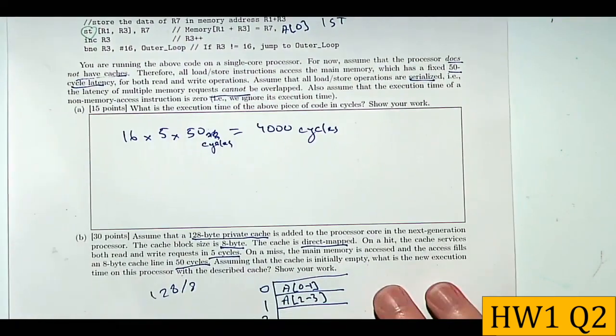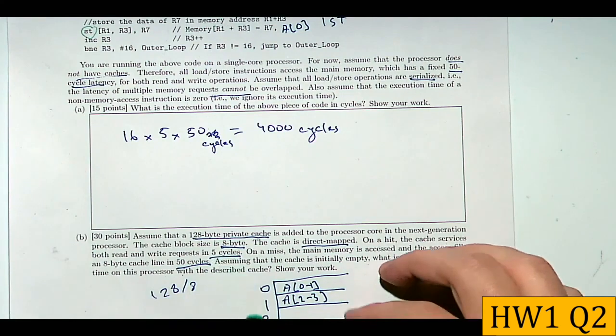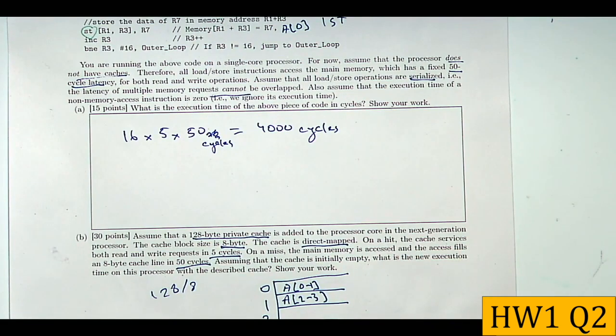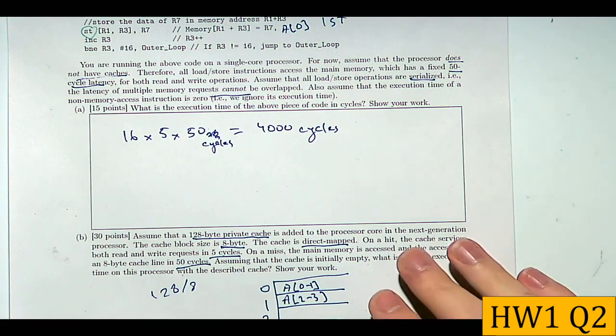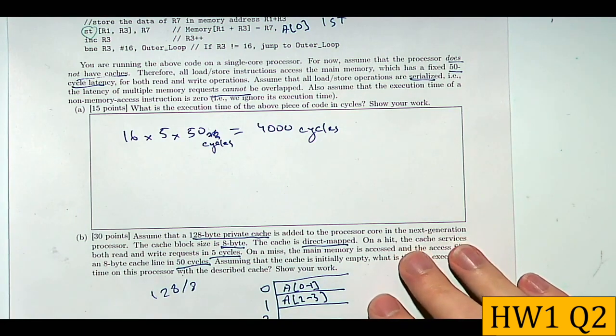For example, here we know that a cache block has 8 bytes. So that will mean we need 3 bits to determine the byte position in that cache block, right? You have 8 different bytes, you address 8 with 3 bits. So you say that we try to address 1 byte. Yes. How do you know we're trying to address 1 byte?